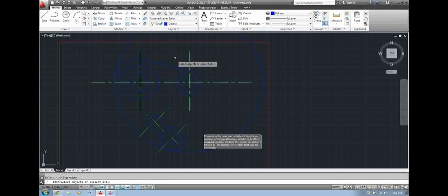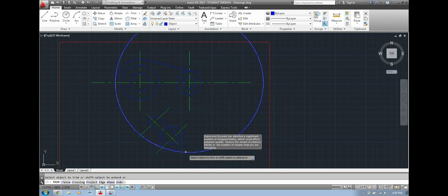Trim command. Okay, notice this one though, something that I didn't mention earlier, is that select all option. You can press enter, and any option that you see that's in those greater than or less than symbols means that that is the default command. If you hit enter right after you select the tool, that's what it's going to do. So why don't we do that? Let's hit enter. Okay, so the objects we want to trim. Okay, by hitting enter, that means every object in the scene or in the drawing is going to be a cutting edge. So, like that cut it.